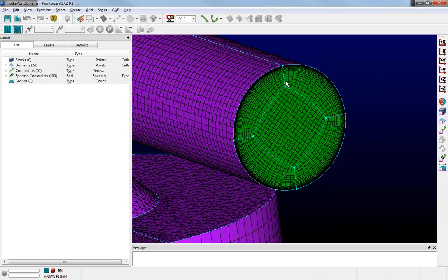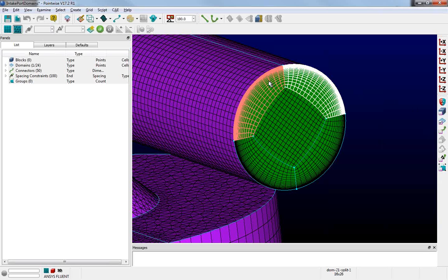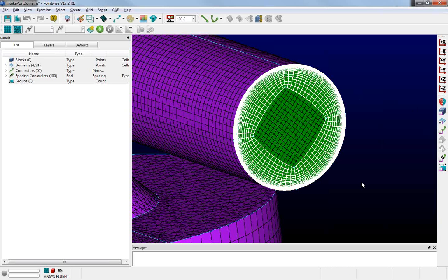So what I need to do is select these structured domains, take them into Examine, and see what my average growth rate is for the inlet domains. I then can use that average growth rate when I'm setting up my T-Rex block as my volume growth rate. So let's go over here and turn on the domain selection mask. And I'm going to select these 4 structured domains that ring the inlet. This is where my boundary layer will exist inside the volume.